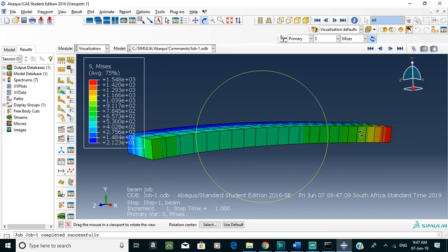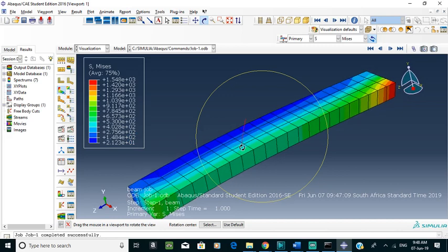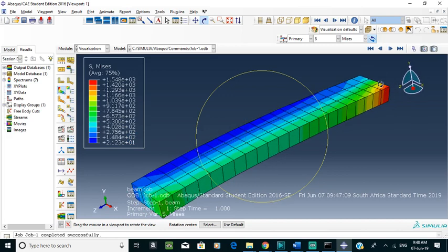So you could see if you apply a stress there, that part of your component that is anchored is going to have some stresses on it. So these parts here are the ones that are prone to fail by fracture. Depending on the material that you have, usually mild steel is more ductile than aluminium, so it might fail in a ductile manner. But then looking at the forces that you apply as well, you might have your ductile material failing in a brittle manner. So depending on the forces you give in and also on the material type, you will see fracture there, and whether it's brittle or ductile will depend on your material.